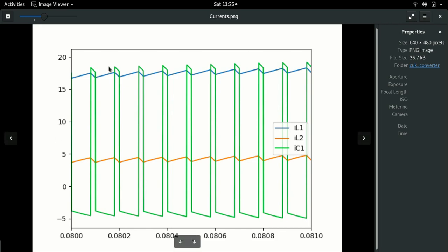So this is one of the reasons why, I would say, an advanced feature of the Cuk converter is that, although we'd need more discussion to go into it, you could wind these two inductors on the same core because they have the same change in current. Therefore, the flux that they will be producing is also changing in the same ratio, and therefore they will not interfere with each other. That's the main concept here.